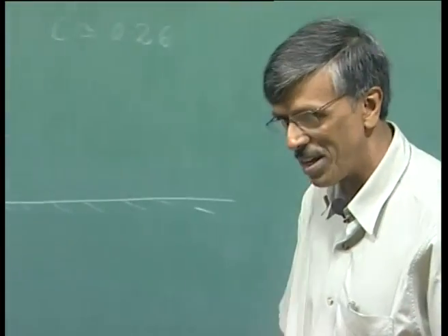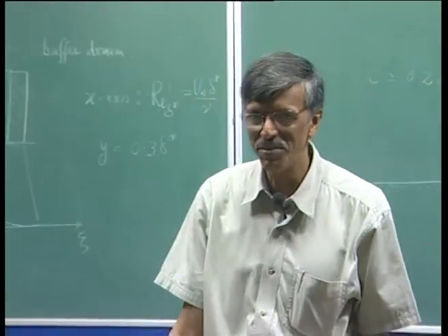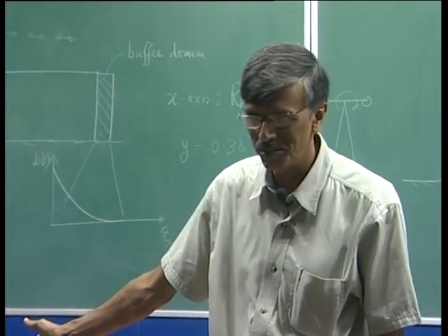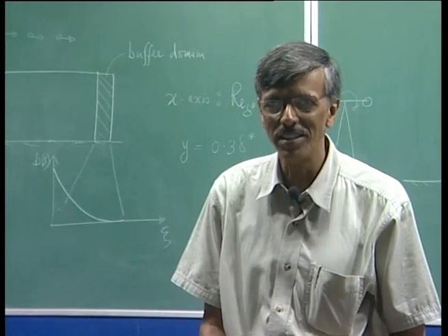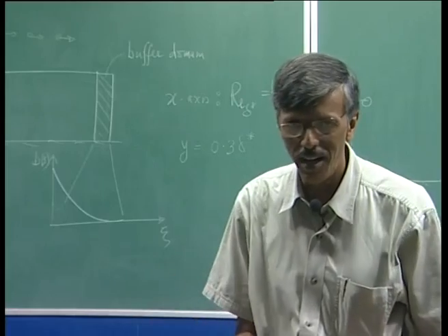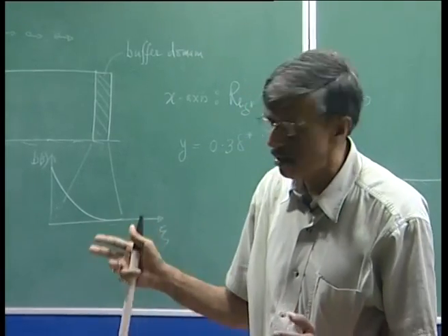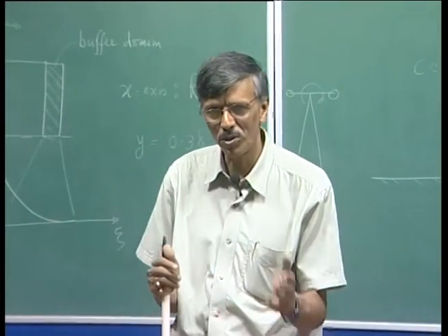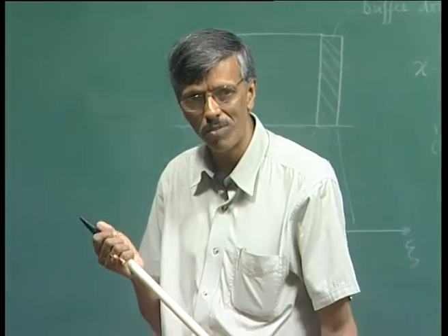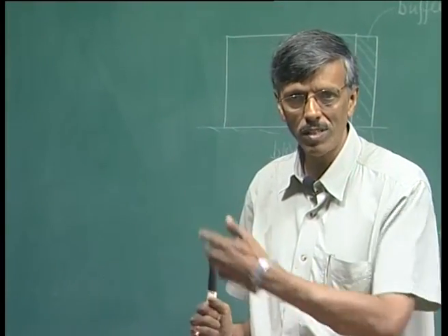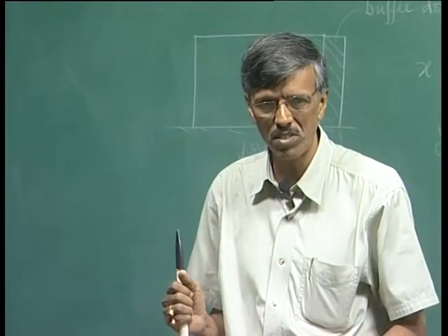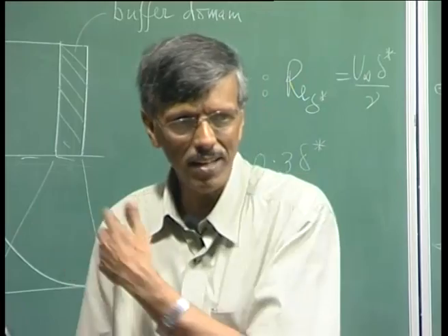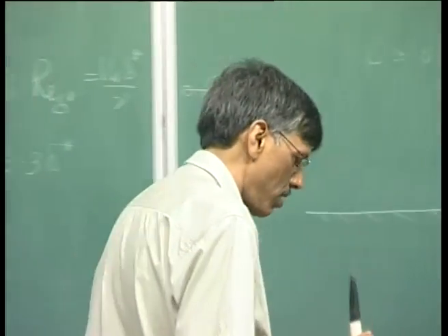So, as time progressed, starting from simple linear stability theory to what I just now discussed, it shows that even under the linear theory ambit, we can see so many complex things happening. We can see pure monochromatic excitation as it was done in the Schubauer-Skramstad experiment. We have also seen the free stream excitation by a simple train of vortices going outside, and that can lead to very complex things, which we called a bypass transition.